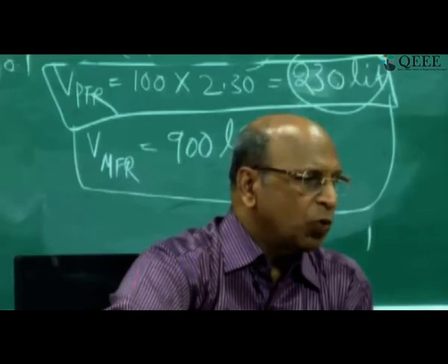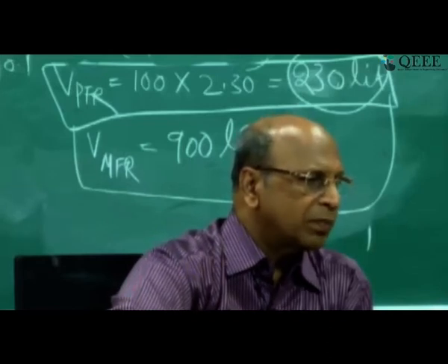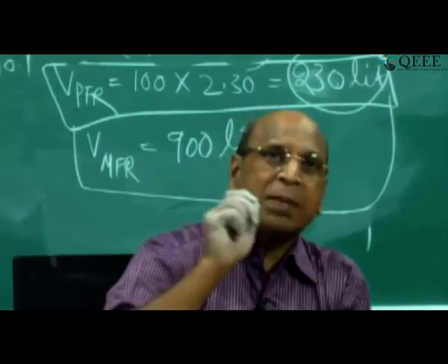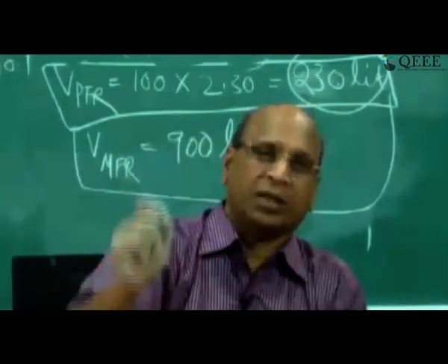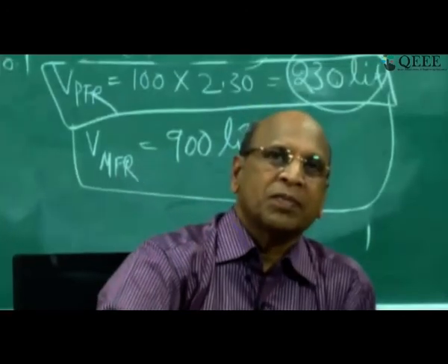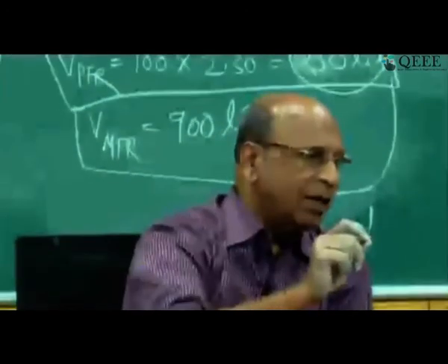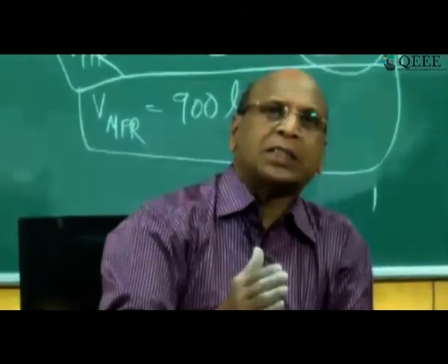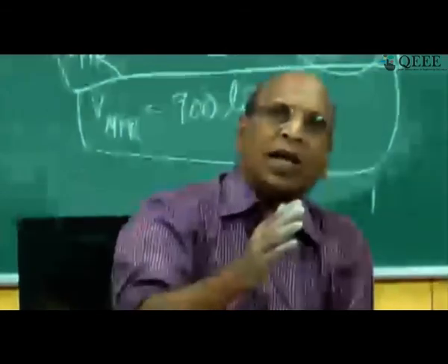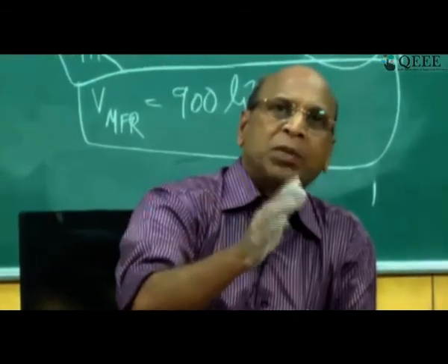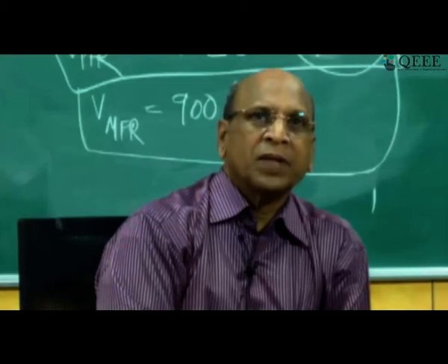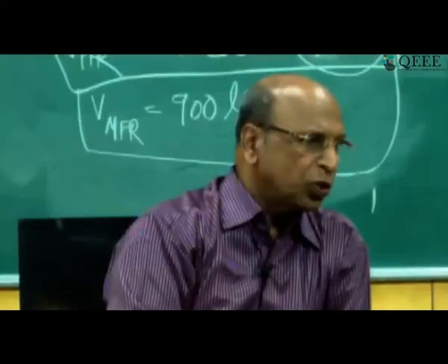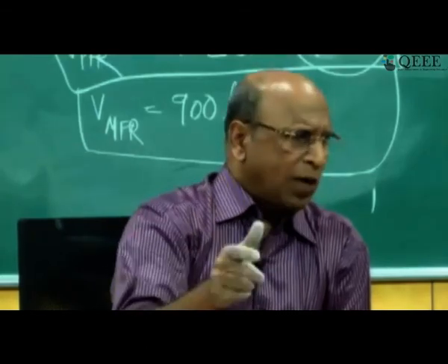Sir, is tracer the only method to find the residence time? No, the tracer method gives you the residence time distribution, and from the residence time distribution you can calculate the mean residence time in that reactor. I don't know whether you have been exposed to residence time distribution. Once more I will repeat.